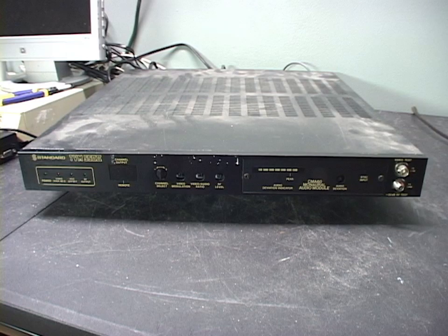These are called T channels, and they're at a far lower frequency than normal cable channels. So you basically have a standard cable television hookup available to your station that you hook a modulator like this onto. It's got to be a special modulator that can modulate on these T channels. This is not one of those. But you basically have a cable subscription feed going into the station. You hook your modulator, your T channel modulator, onto this, and you inject your feed directly onto the cable network, but sort of under the wire, if you will, on one of these special channels.